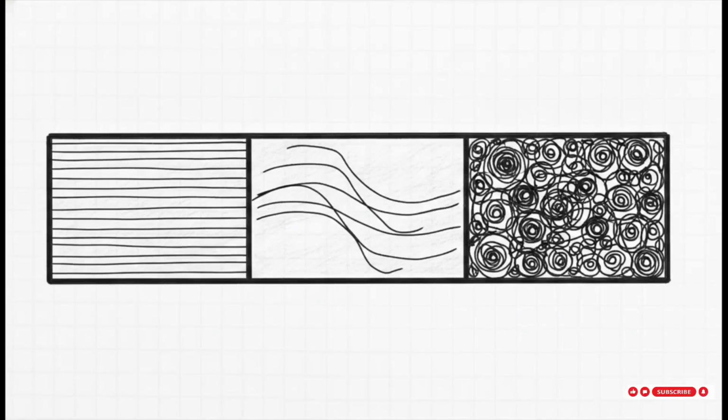And here is the real payoff. We calculate this because of these magic thresholds. If your math gives you a Reynolds number under 2100, your flow is purely laminar. But if that number jumps above 4000, you have definitively entered turbulent territory. And yeah, anything sitting between 2100 and 4000 is just a transition zone where things are kind of up in the air.